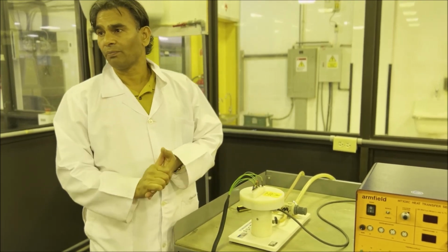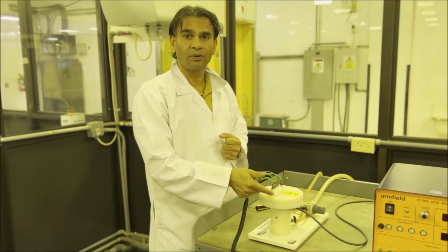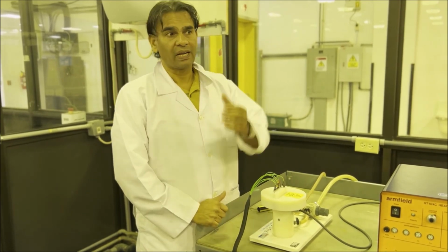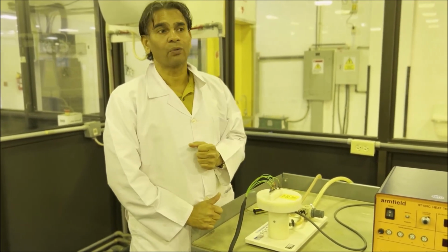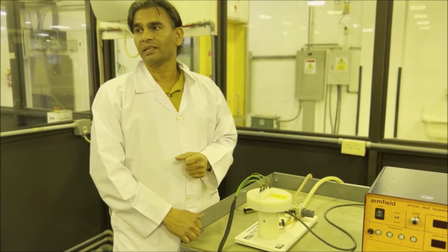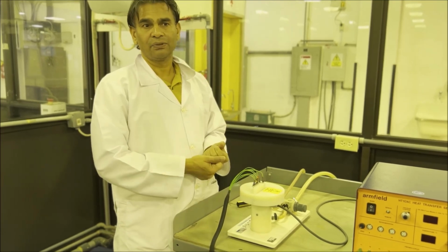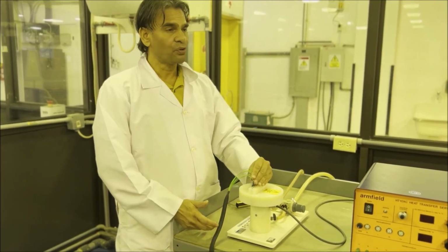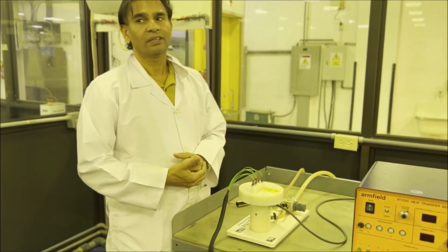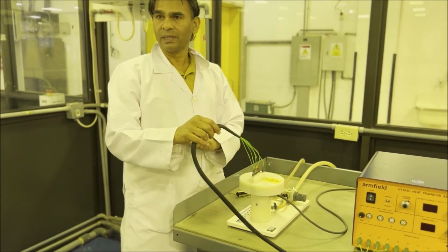At 55 there is no thermocouple, so I need to find the temperature at the outer face. I can add one more objective to find out the outer temperature. If I know thermal conductivity, I can find out temperature. If I know temperature, I can find out thermal conductivity. So the first objective is to find out temperature.